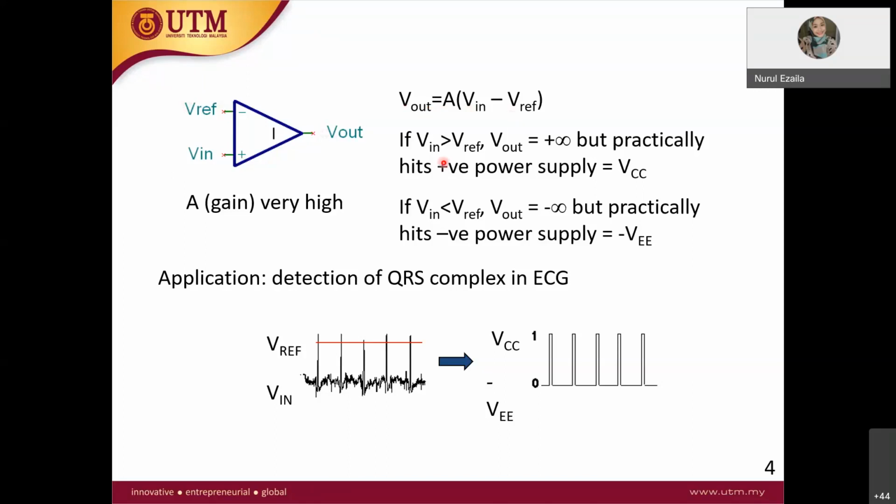If V in is greater than V reference, V out equals positive infinity, but practically it will hit the positive VCC. This is the condition for the comparator.